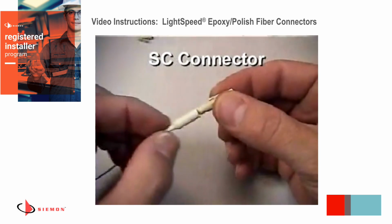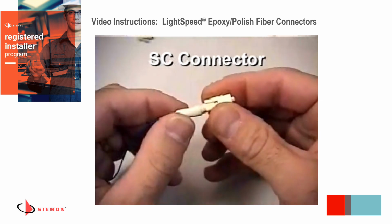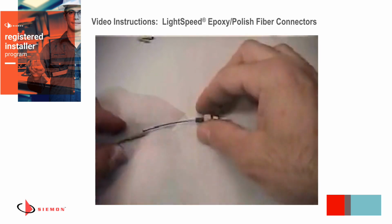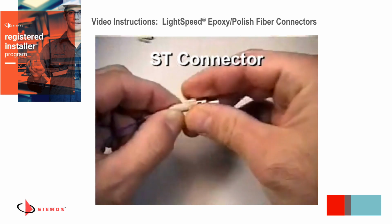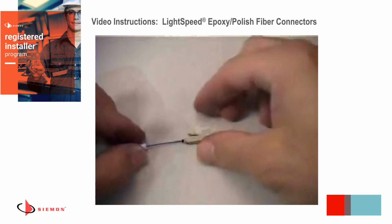Prior to polishing, the boot may be slid into place to provide additional support during the subsequent polishing steps. Be careful sliding the boot into place. Some connector styles may be more difficult than others. Gently work the boot onto the back of the connector, being careful not to slip and break the buffered fiber where it enters the connector.